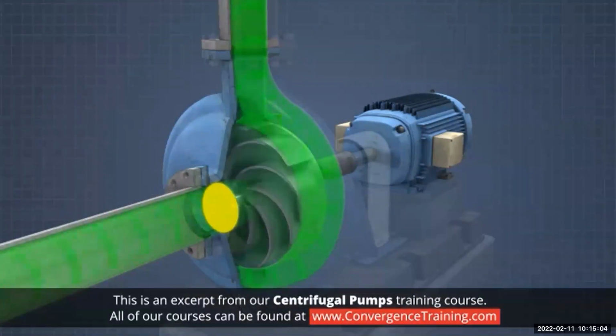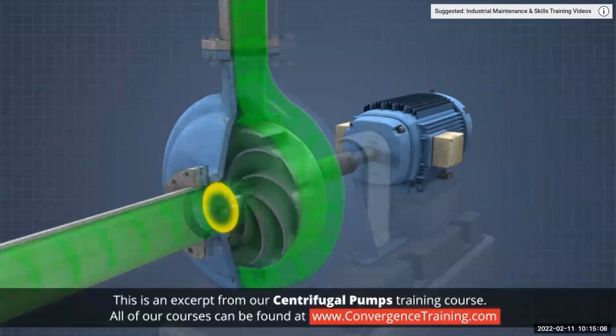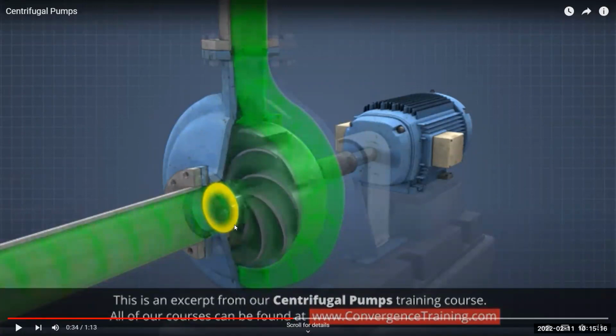This increases the liquid velocity and creates a low pressure zone at the eye of the impeller, which allows more liquid to flow into the pump through the suction inlet. Just to explain this one thing: since the velocity is increasing, the flow is passing with high velocity, which means the flow is not stacking up, right? And if water is not stacking up, obviously the pressure will be less also. That's what they're saying. With high velocity, the pressure is low here.